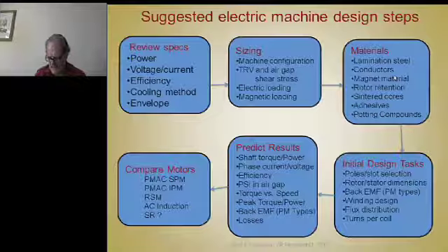They're not able to extract all the heat from the metal plate that's on the bottom of the pack. So they have to take heat off the top of the pack, which is encapsulated with some sort of thermoplastic or epoxy, usually thermoplastics. And you've noticed your Intel microprocessor is a big flat pack thing, and it's got aluminum fins all over the top of it, a little fan. So what that means is they're taking a lot of heat off the surface of that thing.